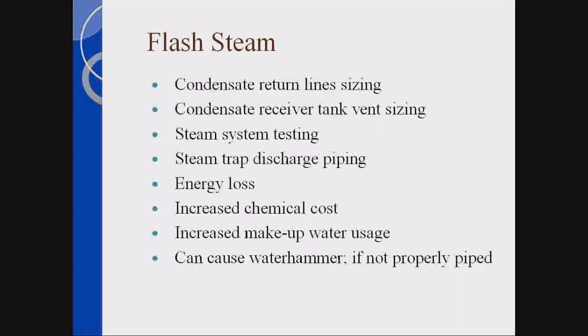Flash steam affects condensate return line sizing, receiver tank vent sizing, steam system testing, steam trap discharge piping, and energy loss. Loss increases chemical costs and increases makeup water. And one of the things flash does is cause water hammer if condensate return systems are not properly piped.